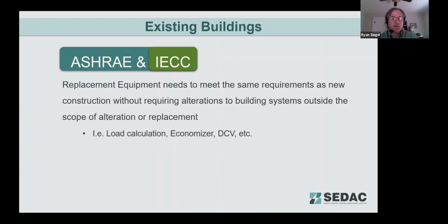That may be where the application of radiant heating might also be useful under ASHRAE 90.1, because radiant heating only has a 4-degree setback requirement versus a 10. So going towards a radiant panel, which, as I recall, commonly is a more efficient delivery mechanism than forced air too, can be useful in that regard.